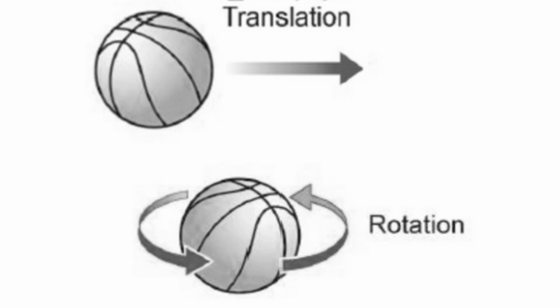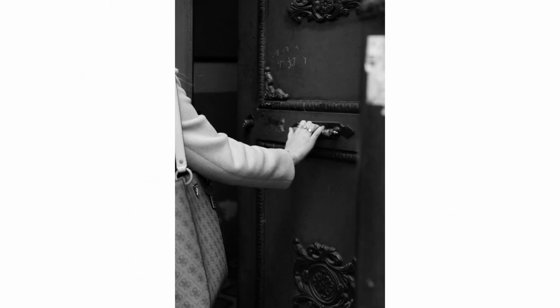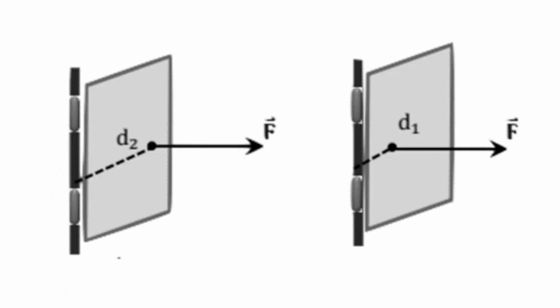See, this is different from the tendency for a body to move, or translate, in the direction of the force. In order for a moment to develop, the force must act upon the body in such a manner that the body would begin to twist. Imagine two people pushing on a door at the doorknob from opposite sides. If both of them are pushing with an equal force, then there is a state of equilibrium. If one of them would suddenly jump back from the door, the push of the other person would no longer have any opposition and the door would swing away. The person who was still pushing on the door created a moment.